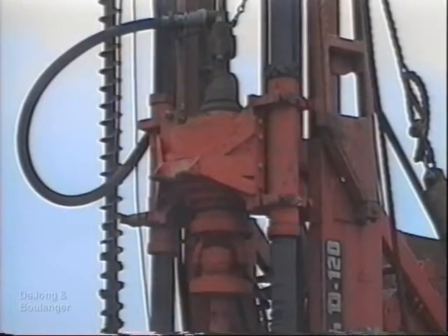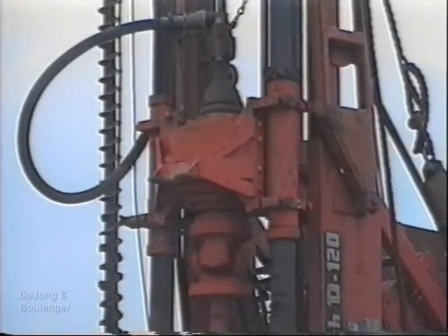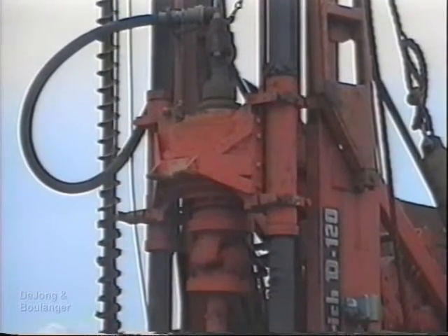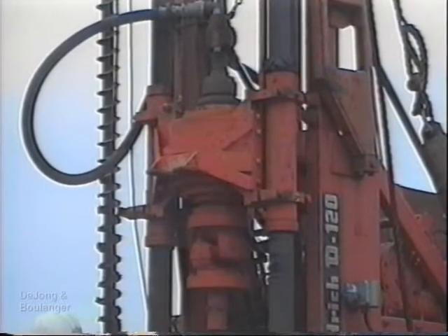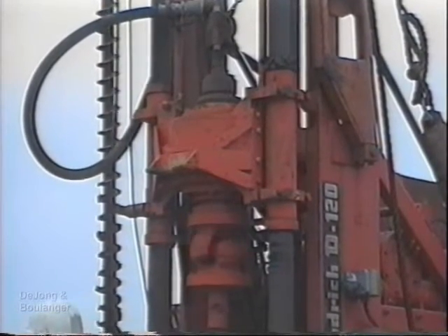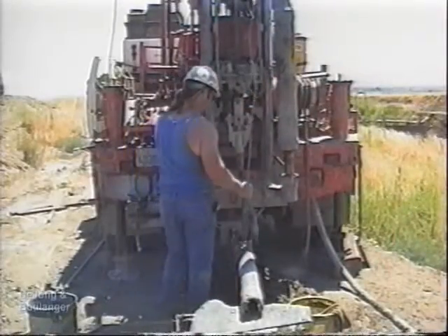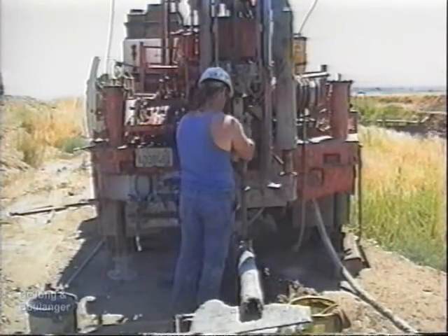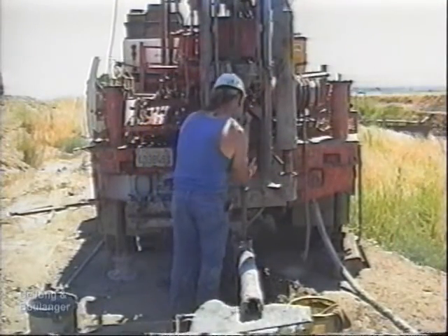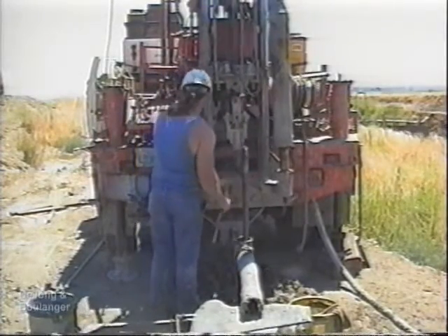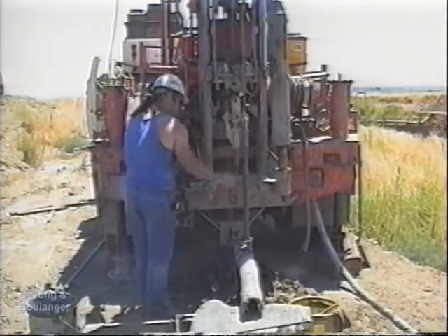The drill head, located near the bottom of the mast, is raised and lowered using hydraulic controls. The drill head is connected to a gearbox which enables the driller to adjust the rotation speed to suit the current drilling conditions. A number of cables controlled by winches run to the top of the mast and back down to the hole. These are used for removing or attaching drill rods, auger flights, or sampling tools.